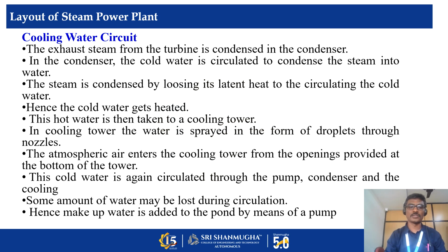This hot water is then taken to the cooling tower. In the cooling tower, the water is sprayed in the form of droplets through nozzles. Atmospheric air enters the cooling tower from the opening provided at the bottom of the tower. The cold water is again circulated through the pump to the condenser. Some amount of water may be lost during the circulation. Hence, makeup water is added to the pond by means of a pump.